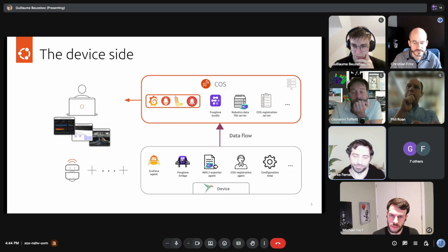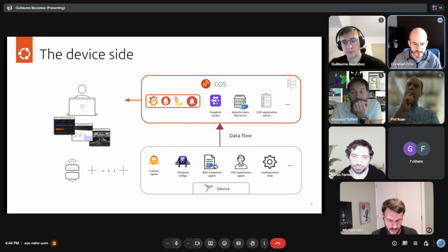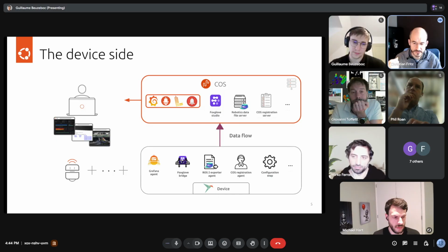Yeah, but the real reason to use MQTT or something like that, which is why we chose it in Transitive, is because you don't want to have a VPN. You want to be able to work. We had 100 robots deployed in hotels and hospitals, and even establishing a VPN is sometimes not allowed by the network you're on. Some firewalls will not even allow you to do that. And then what are you going to do?